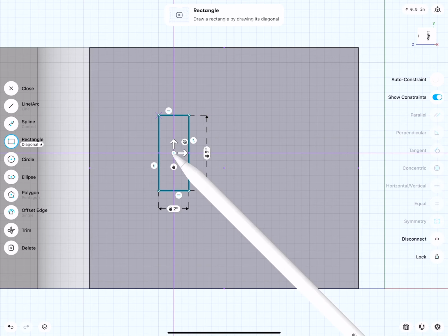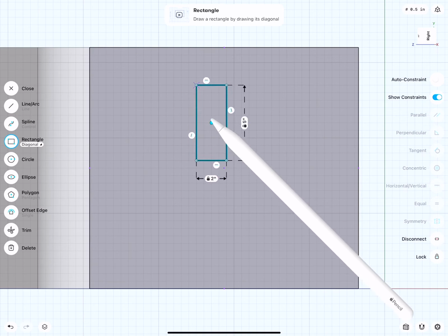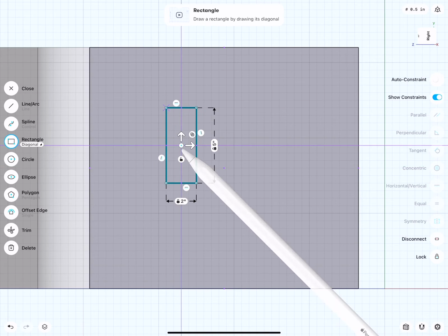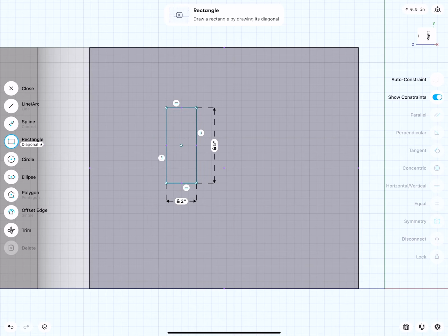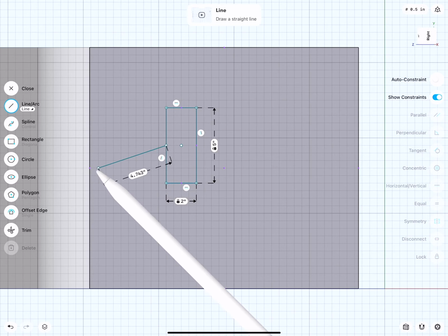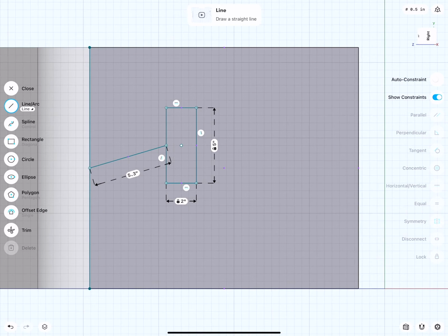Now to center this rectangle on my piece, I can either use the grid. The whole furniture piece was extruded 16 inches, so I can use the grid to position this correctly. Let me show you another step how we can do this when, let's say, the grid doesn't line up. You see that actually we have a magenta midpoint on this line, and there's a magenta midpoint too.